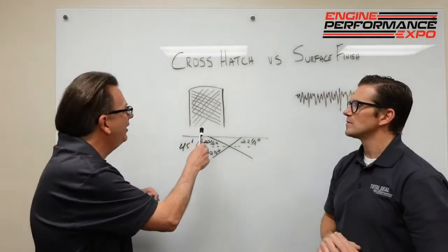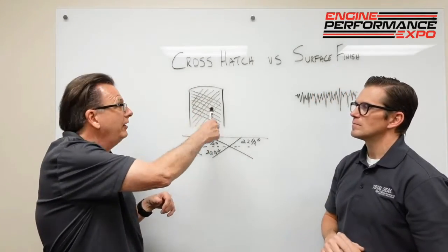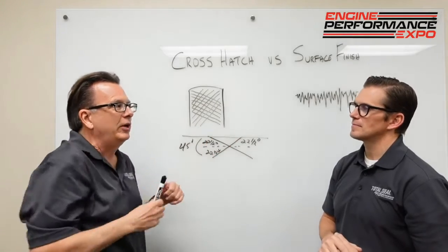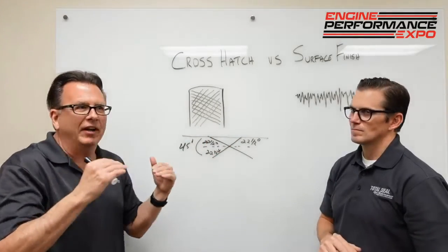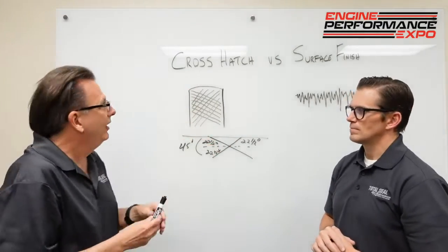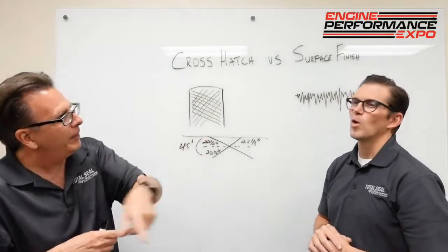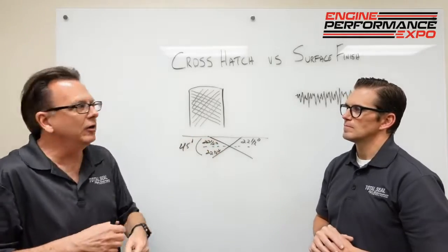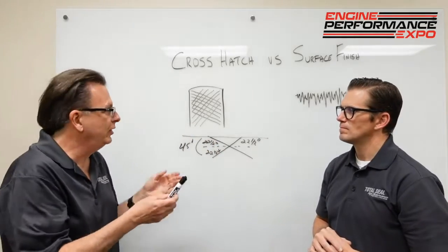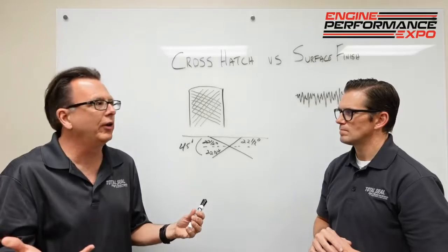We get to a point where now my oil migration is not up and down, it's side to side. Yes. So we create that scraping damming effect. You can actually get into ring chatter because it's become so flat. Think about it like driving over a railroad track, bump, bump, bump, bump, bump. Yeah. So loads, unloads, loads, unloads, and we can get into that effect. So if you get into too flat of an angle, you can create a whole other set of problems.